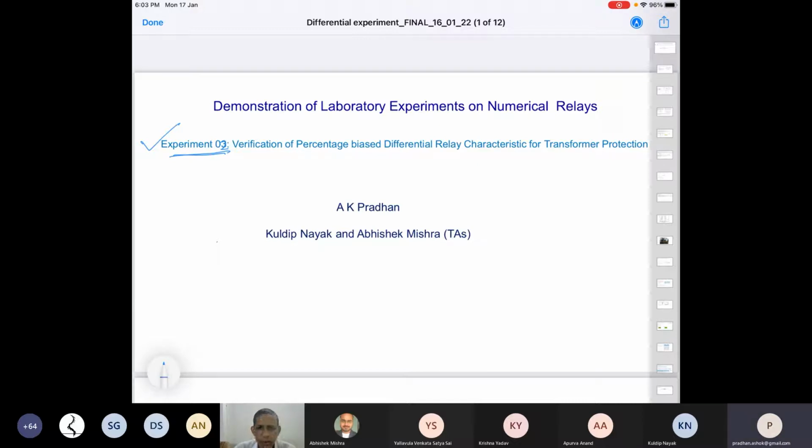So someone may be very good in something. Now overcurrent relay, as you see, takes only the current signals at one place, and then makes a judgment whether there is a fault in the assigned element or section, and accordingly the relay takes a decision to open the breaker associated with that.